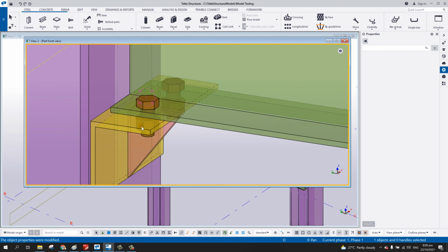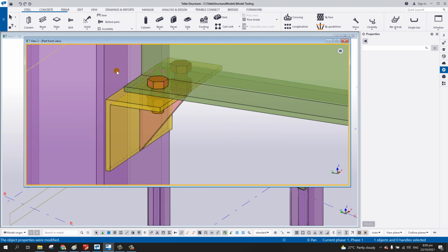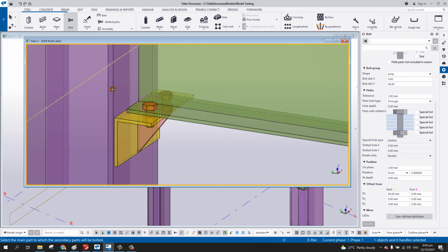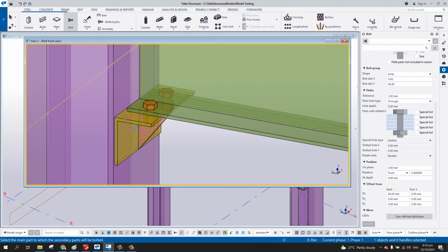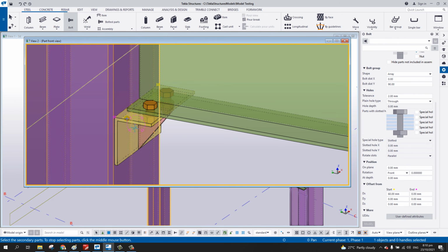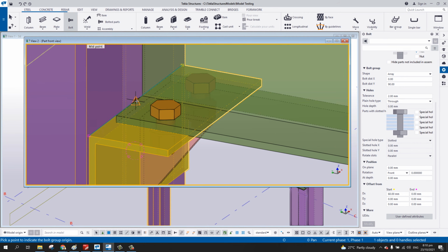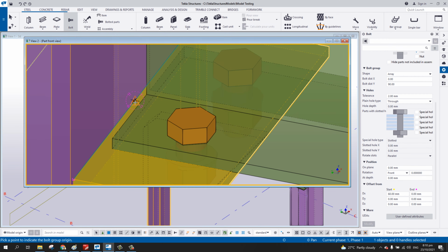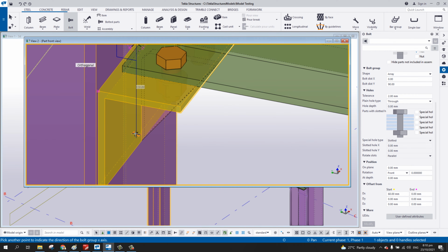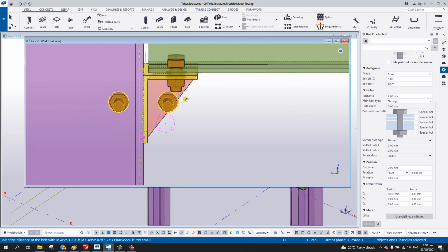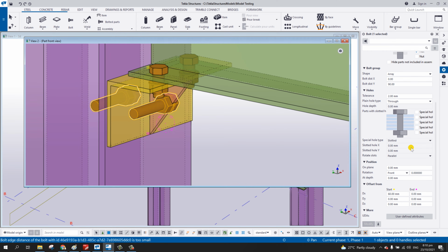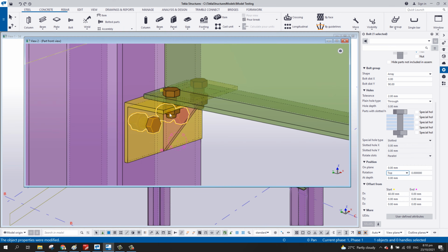And then also the bolt between the column and the angle. Select the column, select the angle, middle button of your mouse, and then again select the midpoint of that angle, and then go down to 5, and there you go. If you notice, the bolt is rotated, so no worry about that one. You can just simply change this one to top, and there you go.